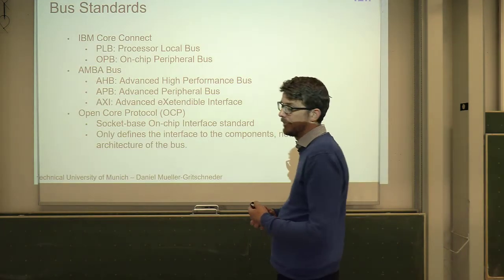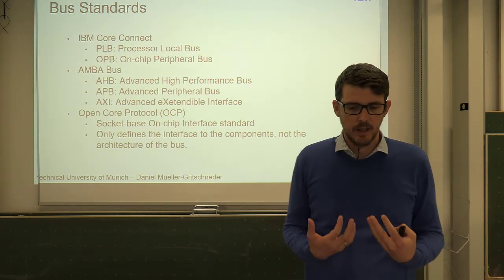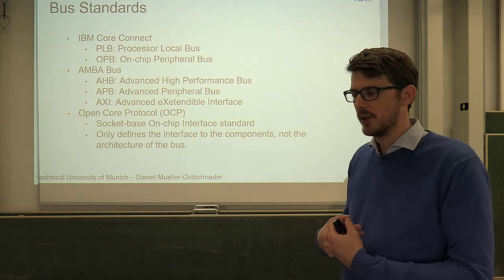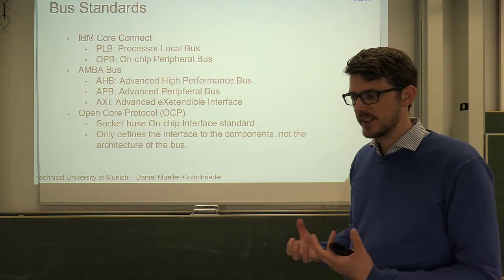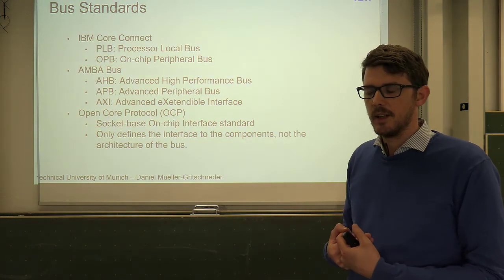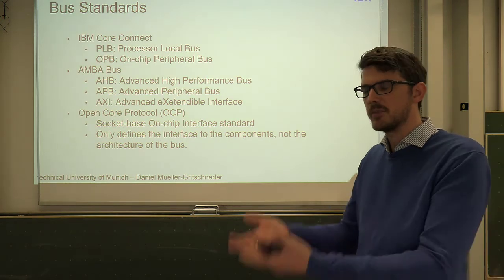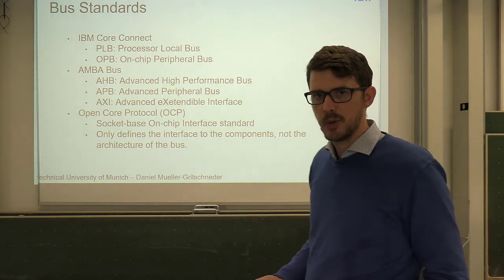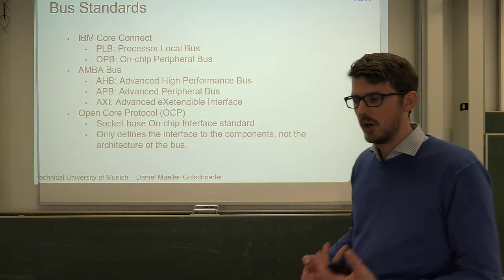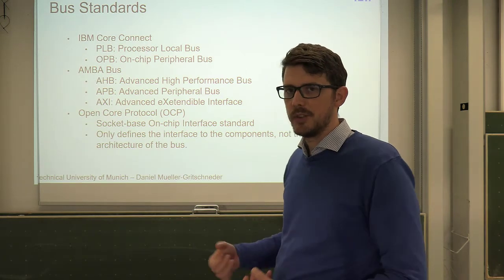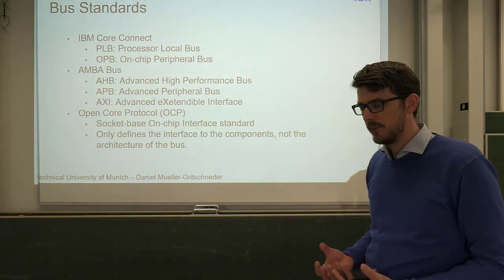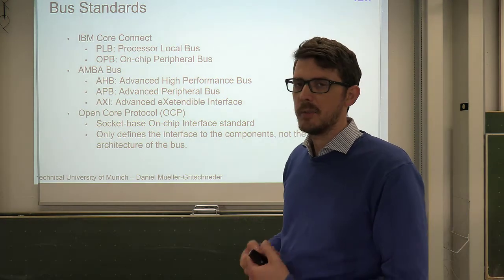Okay. Now, as I said, if you decide this is the protocol I want to use, and then you're designing all your state machines for this protocol, this is a lot of effort. And designing these buses is not easy. It's actually quite complex digital circuits, right? Even though they transmit information, they don't do any big computation. Doing it the right way becomes very, very complex due to supporting all these features like split transaction, pipelining, and so on. And therefore, what people did is they basically came up with standards.